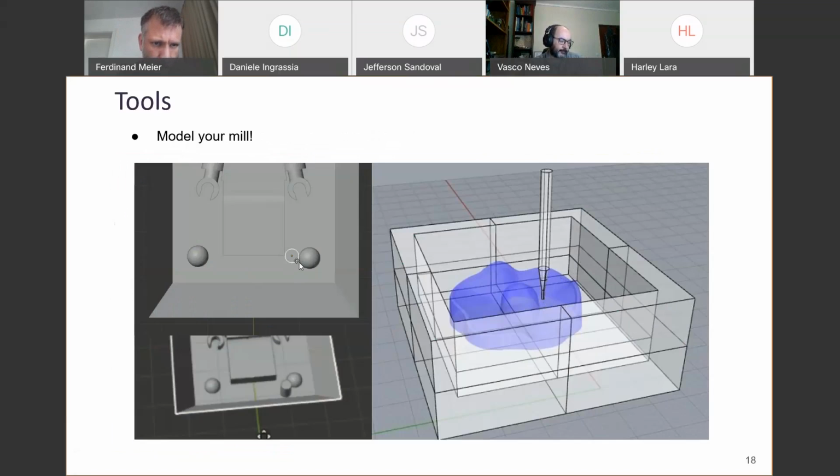Also look from top. So this is my 3 mm mill, and I can move it all around all my features and see, do I have 3 mm here? Do I have 3 mm here? Do I clear to the side walls? Yeah, so this is going to cost you a little time in the design phase, but it's going to save you a lot of time once you start milling.